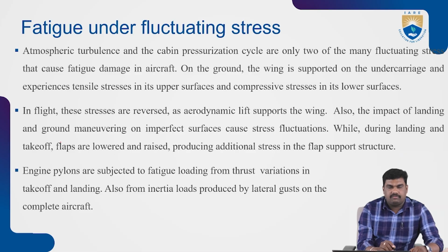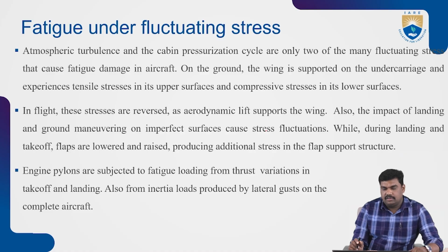Also, the impact of landing and ground maneuvering on imperfect, uneven surfaces causes stress fluctuations. During landing and takeoff, flaps are lowered and raised, producing additional stress in the flap support structure. Engine pylons are subjected to fatigue loading from thrust variations in takeoff and landing.